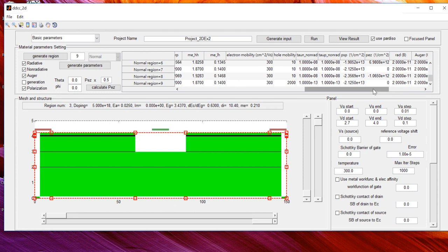But what I would suggest is that you just keep my setting and change it slightly, because in our experience, if you put a very high carrier density, the convergence speed is slow. It's a numerical issue. If you put a lower carrier density with higher mobility, the convergence speed is faster, but they give you the same result because the resistivity is the same. So usually you put this, but I should not put it in layer 9. Do you know what I mean?